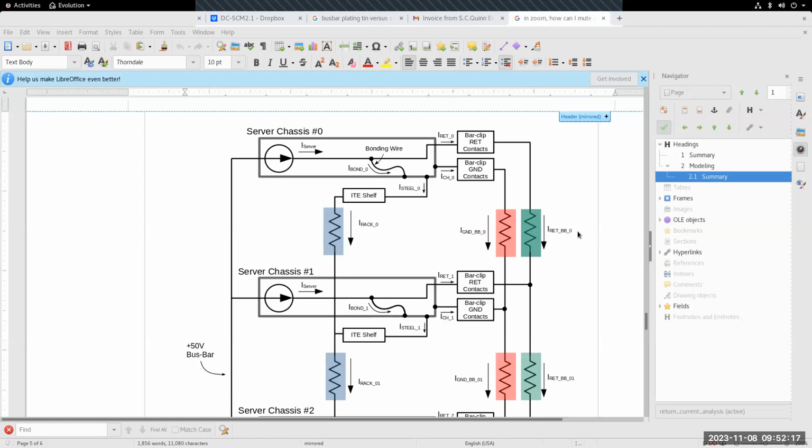We were using a matte tin over nickel plating on a copper bus bar with a connector not very dissimilar from the ORV3 one. And we ran into a pretty significant problem of fretting corrosion on the matte tin due to micromotion of the mated surfaces, just from shipping and even from just systems sitting in the data center.